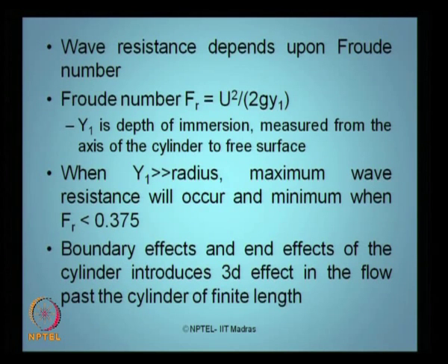The boundary effects and end effects, if you talk about the length of the cylinder, covering the ends of the cylinder, etc., will induce what we call a 3D effect on the fluid flow in the vicinity of the cylinder if the cylinder is of finite length. The same story happens in the case of vertical cylinders also. In horizontal cylinders the story is again the same.